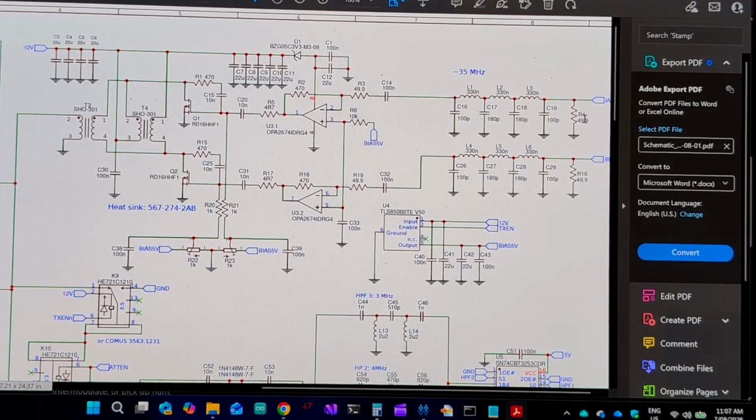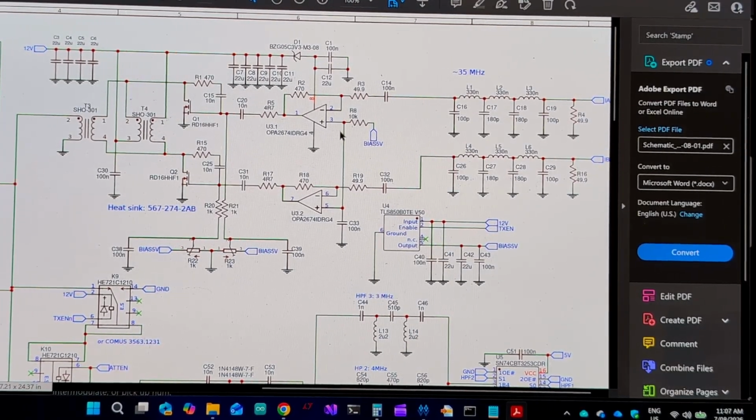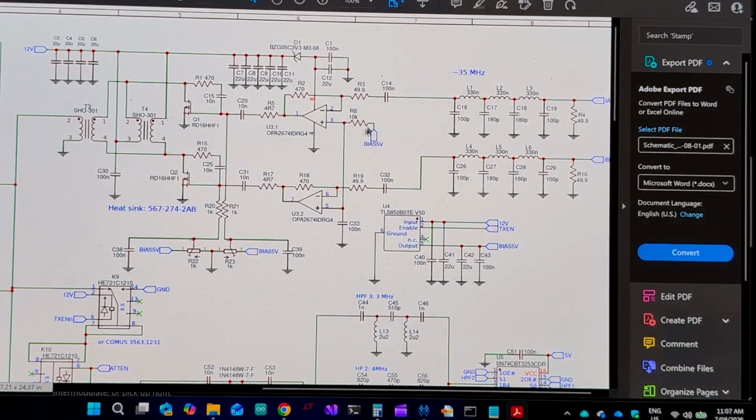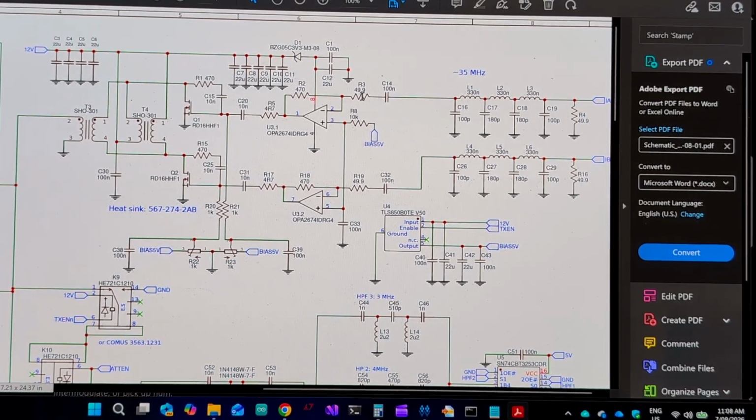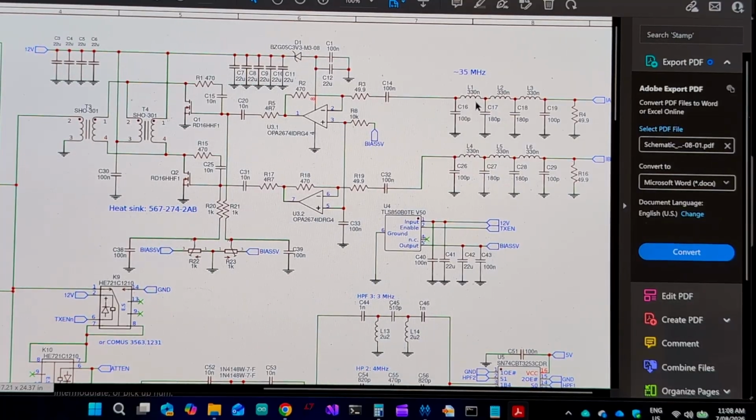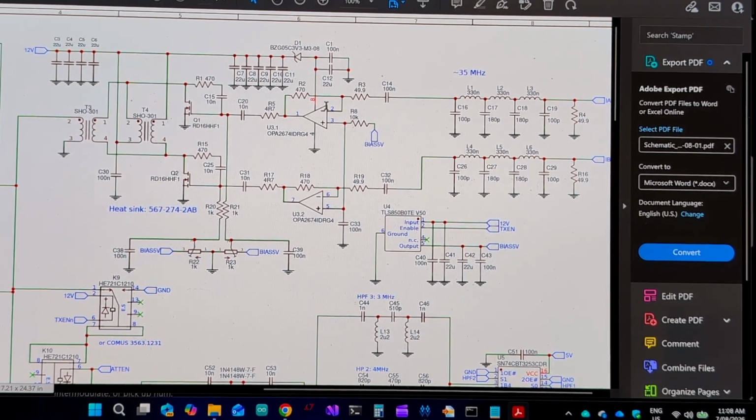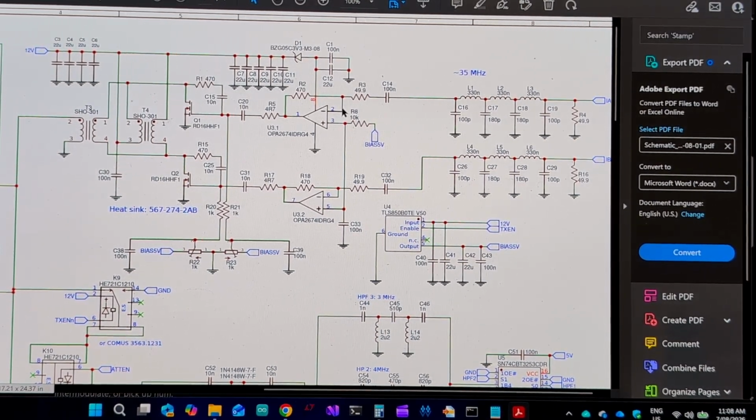So the resistor here is a 50 ohm resistor, a 50 ohm filter, and the op amp, the OPA2674, is a high speed, wideband, high current output op amp. Which means, and we're driving the negative input. So this 50 ohm resistor provides the 50 ohm needed by the filter, and has a gain, what's that gain? A gain of around 10.